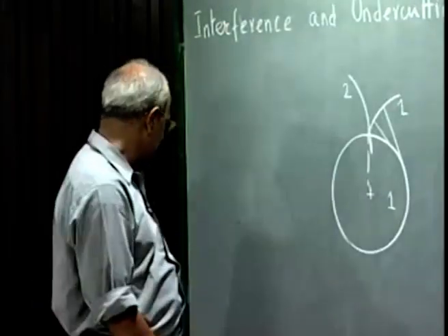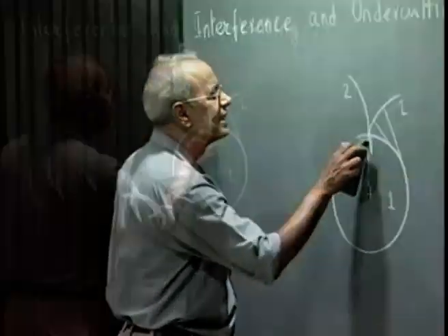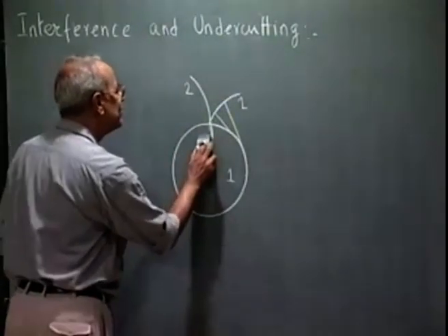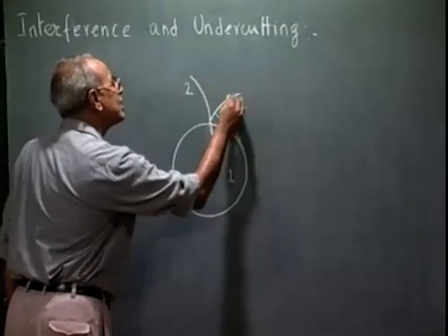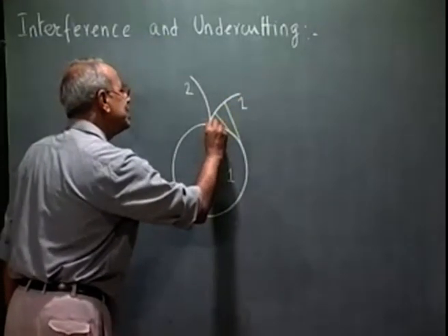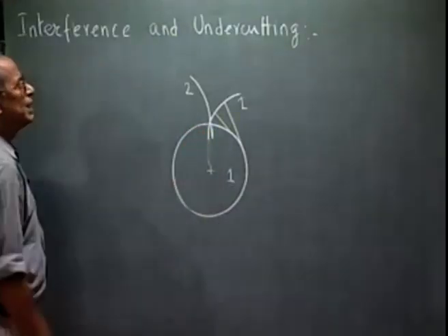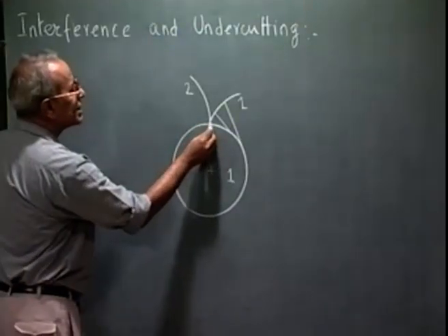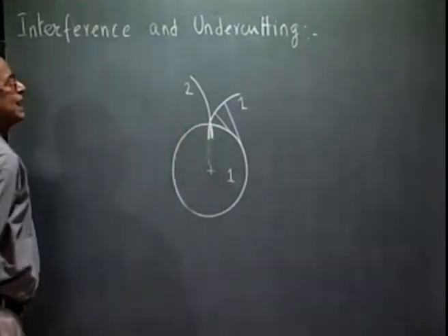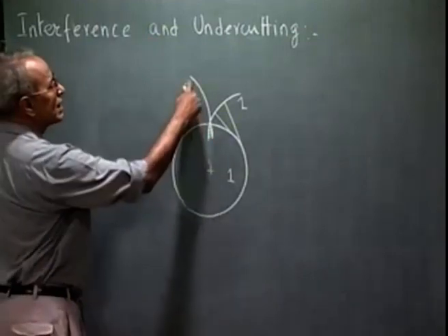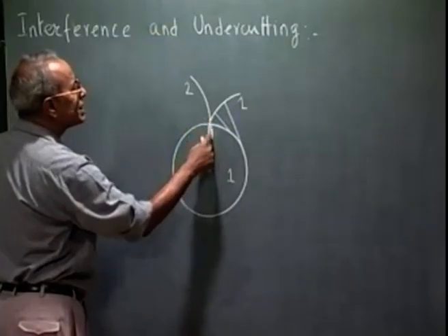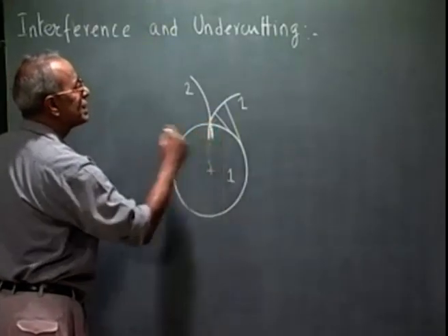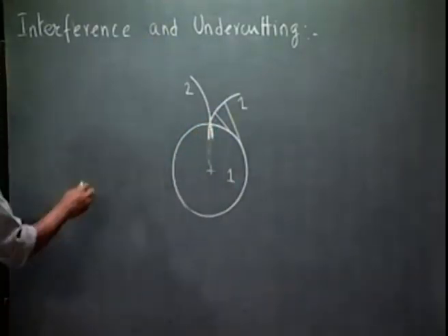So, there is no conjugate profile. So, what can one do? One can extend this involute of gear 1 maybe radially. Even then there is interference. As we see, this tooth will interfere with this tooth because this tooth wants to occupy this position, whereas this tooth is lying there. This is called interference.